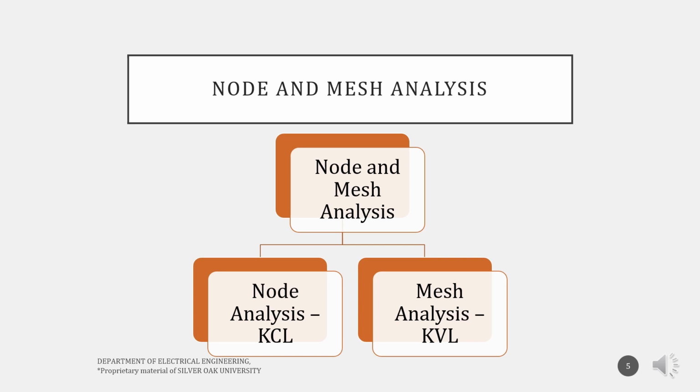Node analysis is a method that allows us to determine the voltage at various nodes in a circuit. A node is a point in the circuit where two or more components are connected. By applying Kirchhoff's current law, KCL, which states that the sum of currents entering a node is equal to the sum of currents leaving that node, we can set up a system of equations to solve for the unknown node voltages.